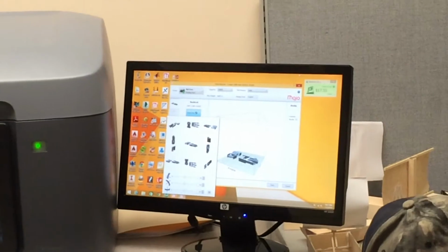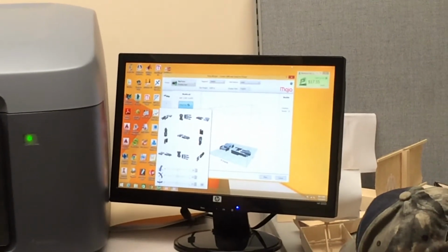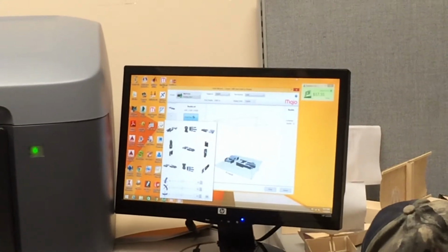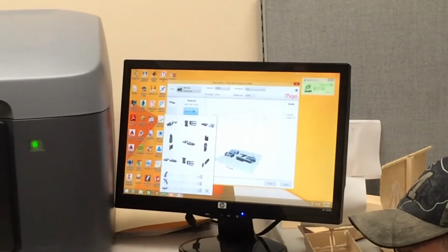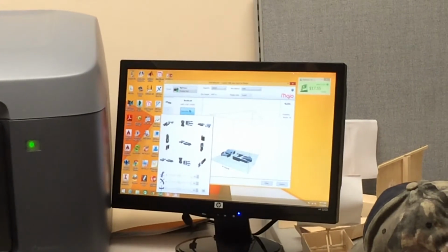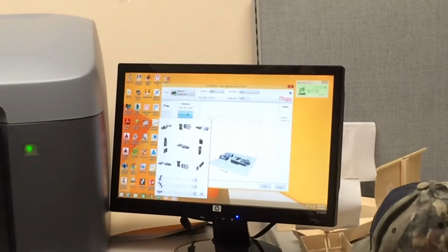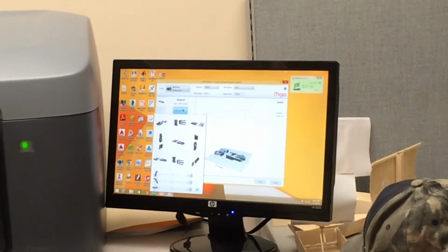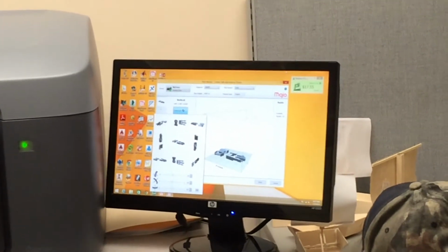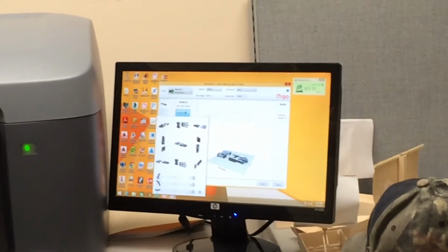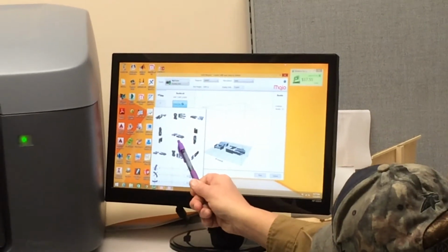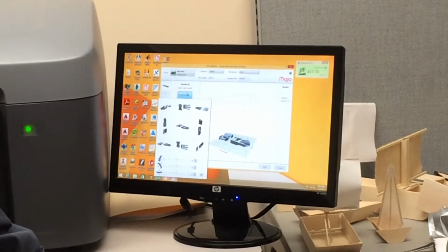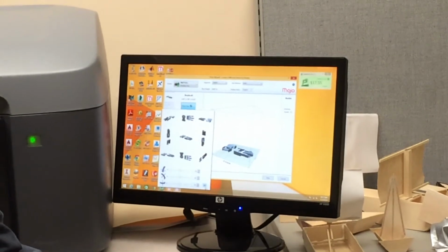So certain orientations are going to give you less support material than others, but also if there's a particular direction that needs to be strong, and you can keep that in the X or Y plane, it's going to be overall stronger, because the X and Y planes will be layers this way. This is the Z direction, and that's the weakest direction for any 3D print, any FDM print. This one obviously pre-selected that one, and I'm okay with that. So I don't need this.